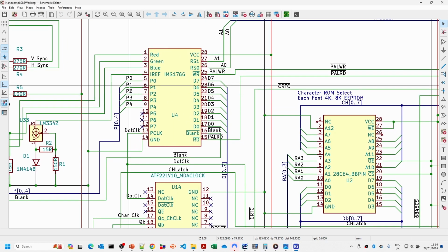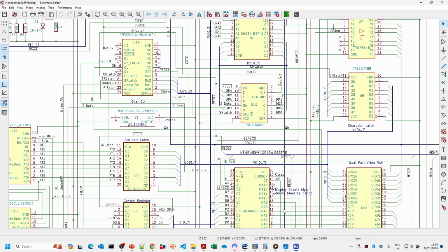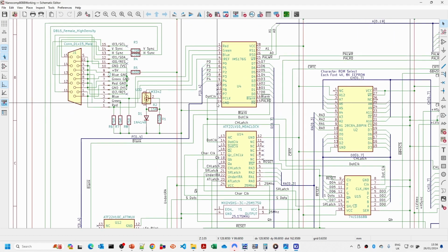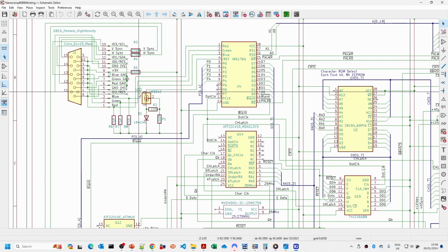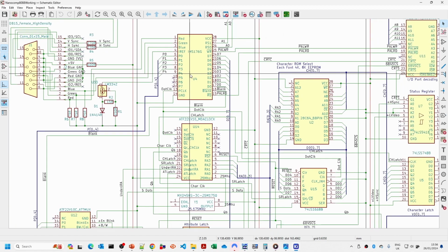We're just going to wire up temporarily to the CRTC address outputs here, and what this will do is, once the palette has some different colors loaded, then we should see the different colors. We're going to need to wire up the connector here with all these various resistors and the current source, and once that's all wired up, then we should be able to get some video signals out of this.